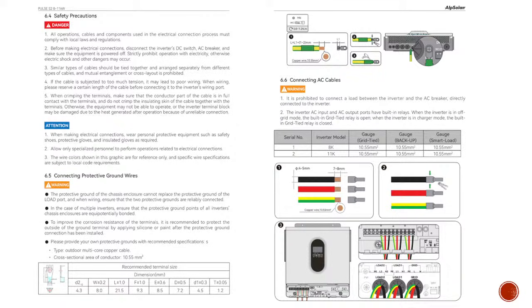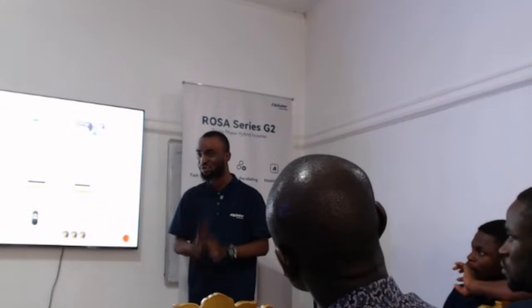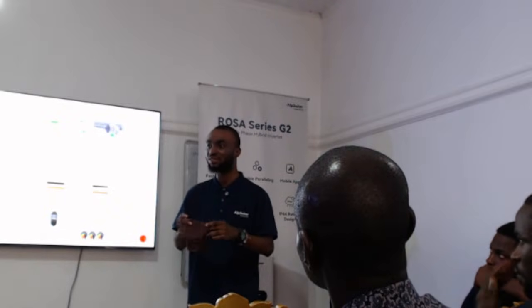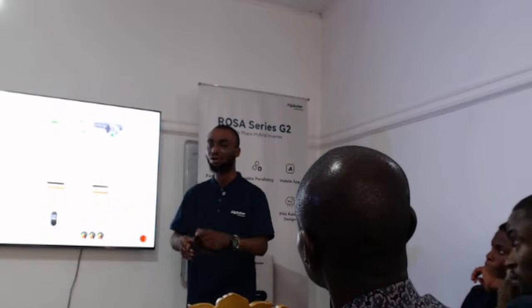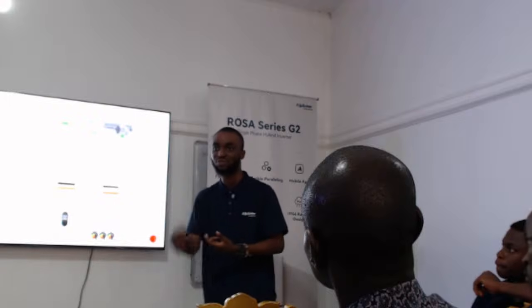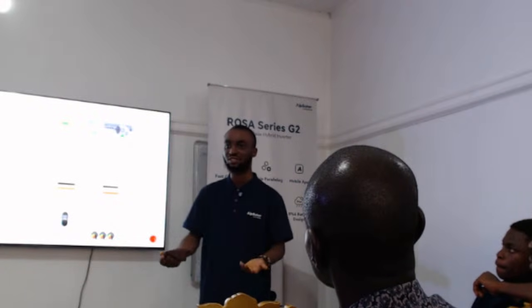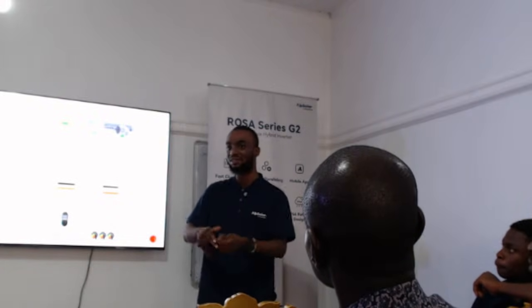I've seen this. This is one of the major problems we face as after-sales engineers. You go to a site and you find out that the most basic problem was that the cable was not properly crimped, and it's not making the right connection with whatever you are plugging it to, maybe the breaker or directly to the inverter. You will see partial contact. There was a particular place we went where they said the inverter is not working, not knowing that the cable they passed through to the PV breaker did not make proper connection, probably as a result of how they crimped it.